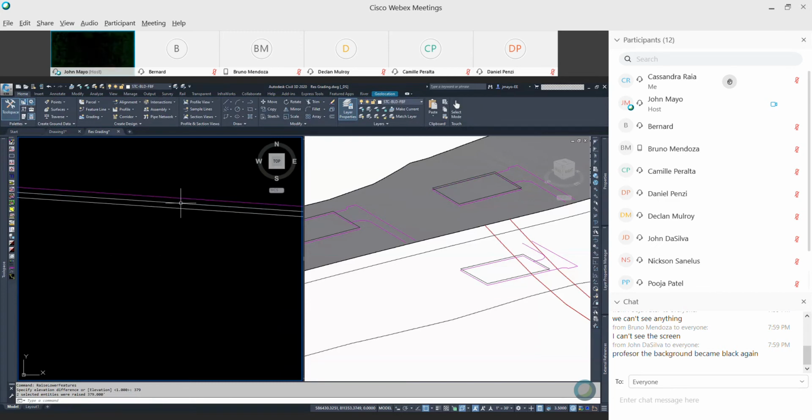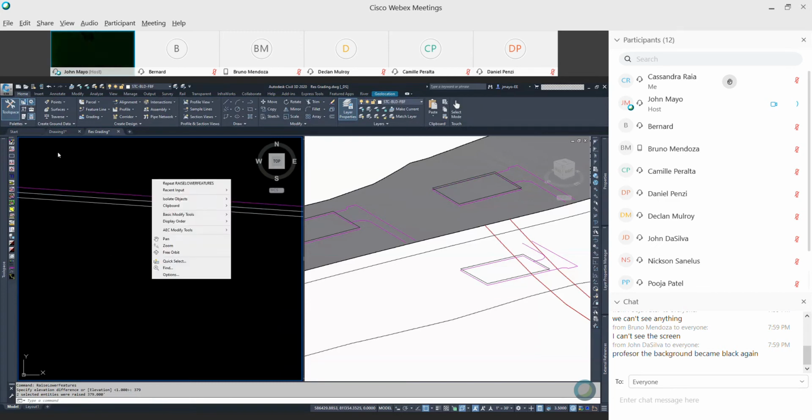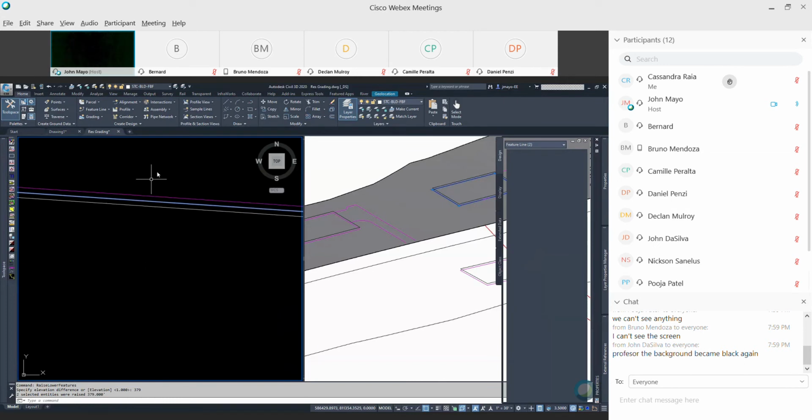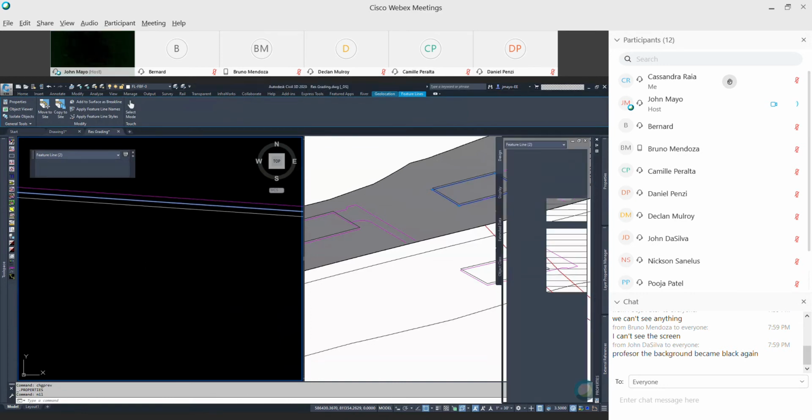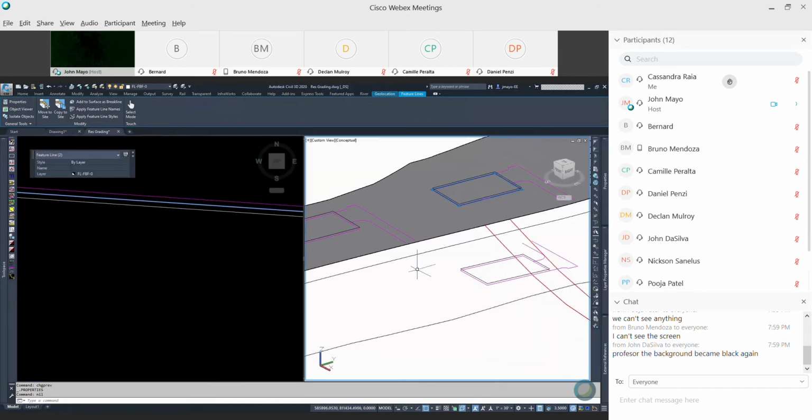I wanted it to be 8 feet lower than that. So I'm going to use my change previous, and I am going to lower that. I'm going to repeat that command. And I'm going to lower them now minus 8 feet. And that puts my 2 basements back where they should have been that I just messed up.